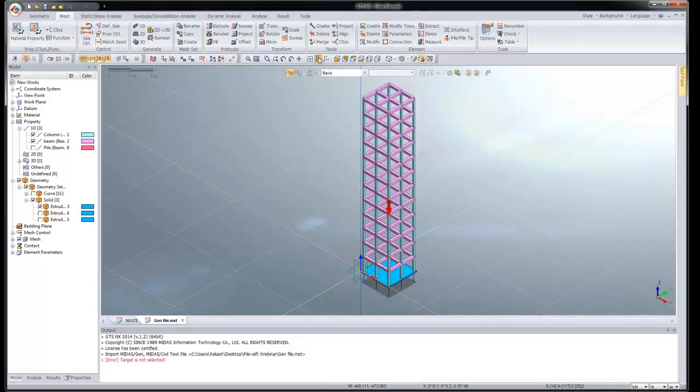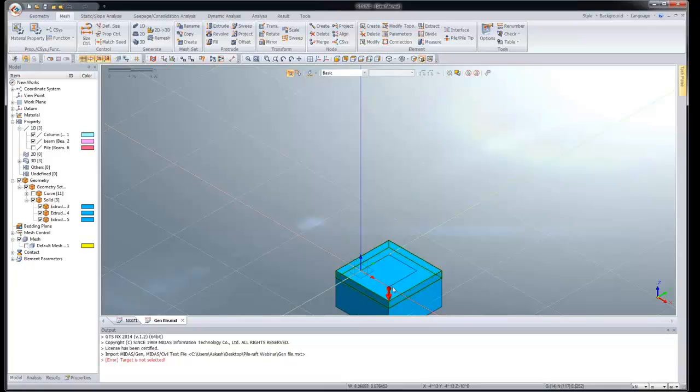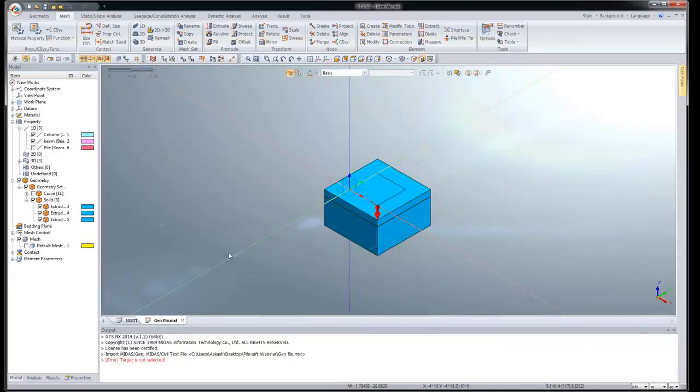First of all, we'll assign the ground material properties and then we will generate the pile. So just activate the solids and I'll just deactivate the mesh set. Default mesh set is basically the mesh set for the building which we have imported. So this is the model with me right now. Go to mesh, go to 3D mesh.